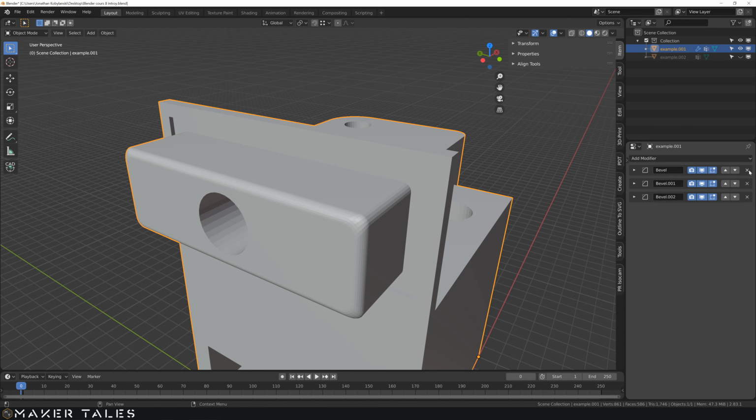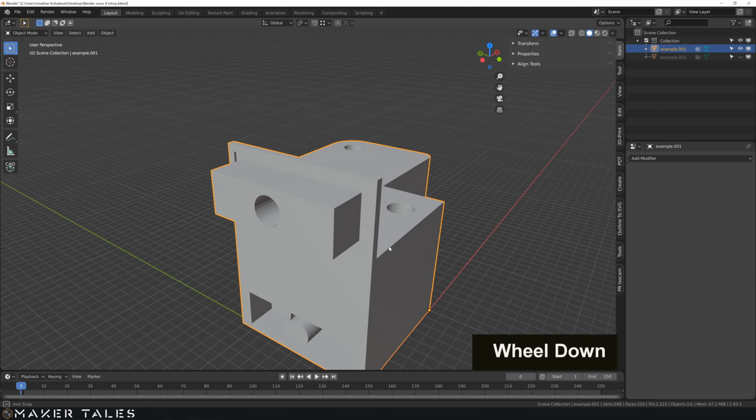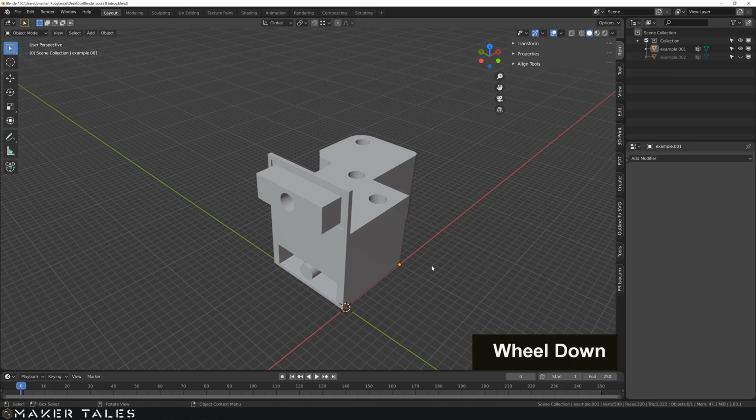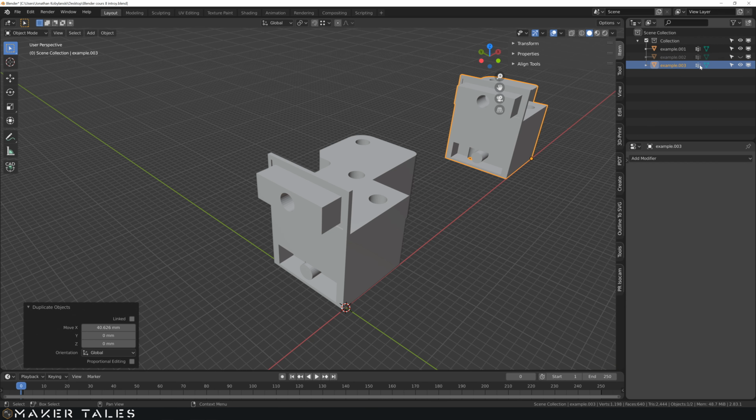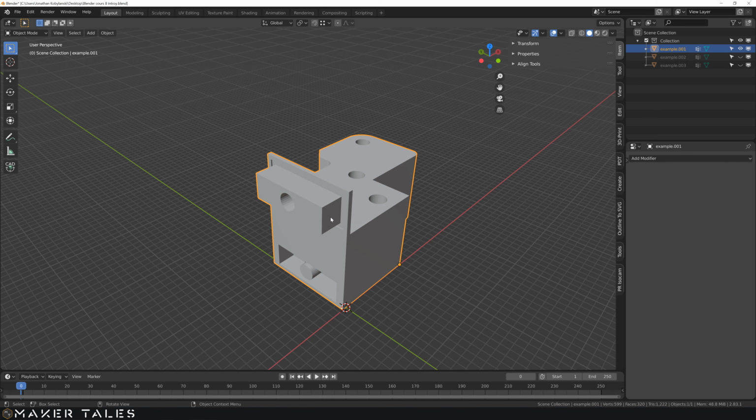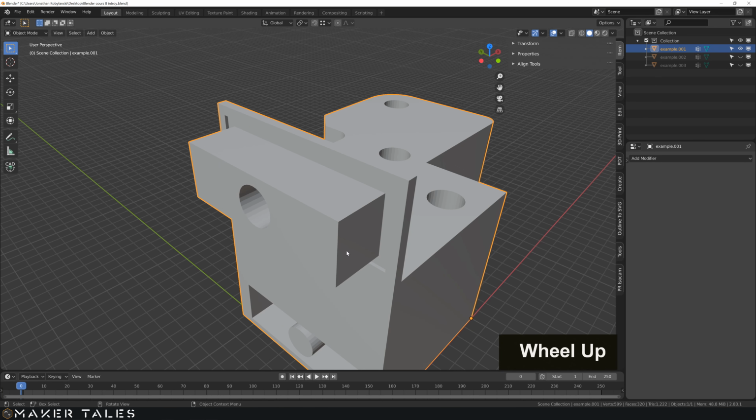Modifier. Having said that, me personally, the way that I use bevels is I use them destructively, in the sense that once I have a roughed out shape like this, I would go ahead and I would do a hard copy, move this out, rename it, hide it, chuck it into a collection of backup, and now I start doing my beveling. If there's a point that I know I've done all my beveling that I'm happy with, then I will do another save at that point.